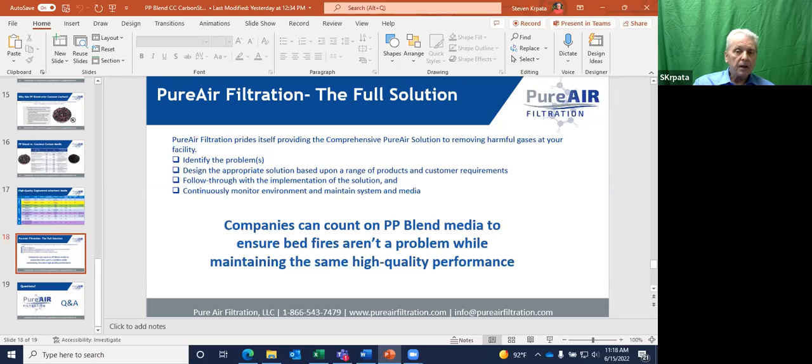If the media gets used up sooner than planned by the calendar, then the space is unprotected, and the cost of the equipment and the operations is astronomically higher than the cost of a media changeout. If the media is not used up when the calendar says it's supposed to be changed out, then we're spending money unnecessarily before it needs to be spent.